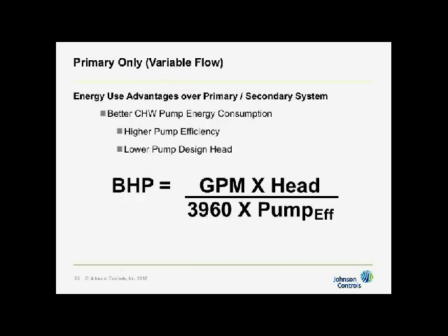VPF also has the advantage that it improves the energy use over primary secondary. The first reason is that we have better chilled water pump energy consumption. One reason is because we have higher pump efficiency. This is because we're combining the primary and the secondary together and having a higher head with the pumps. Typically going to higher heads moves you into a more efficient region of most pump curves.